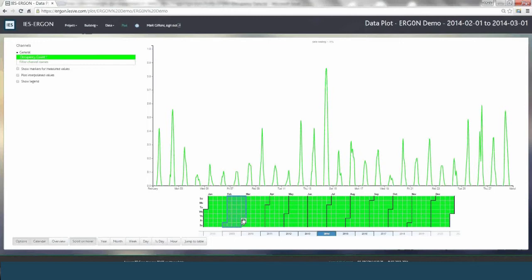You probably find if you're looking at BMS systems in particular that the data yield can be quite patchy, just due to maybe communication issues on site, whereas your metering infrastructure tends to be more robust. So if you're looking at main utility meters, chances are your utility company will have a good system in place because that's what they're using for automatic billing. But the BMS is certainly a bit more patchy.